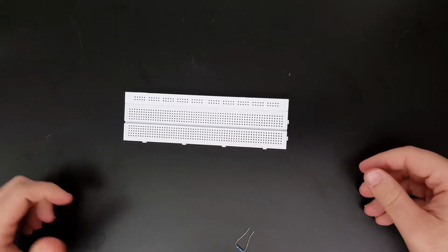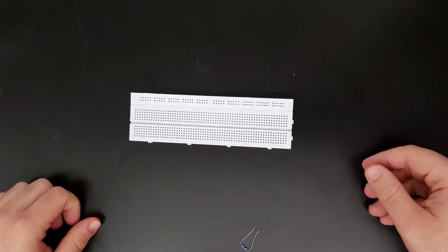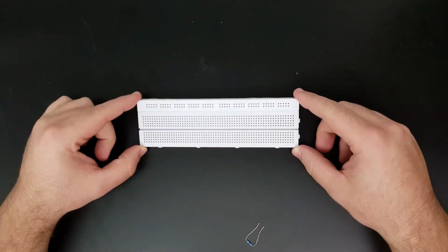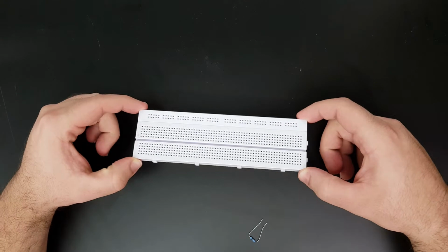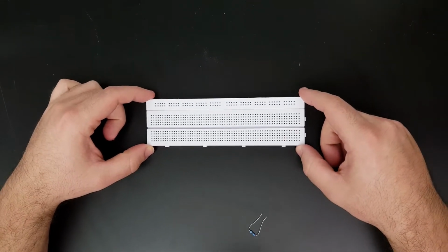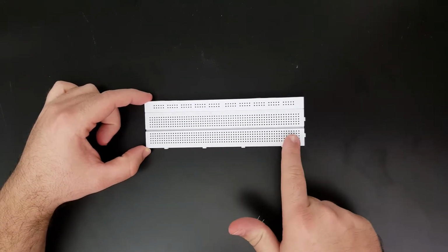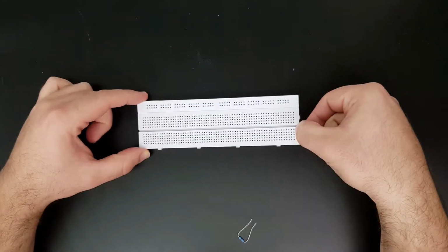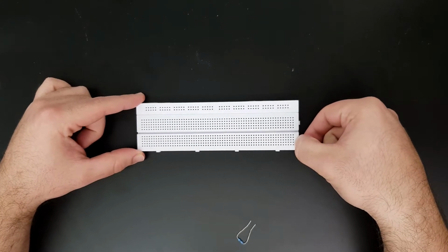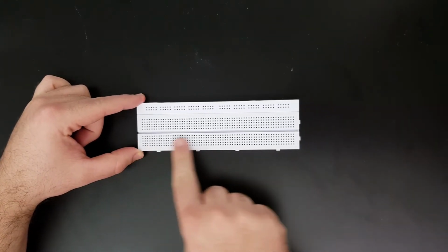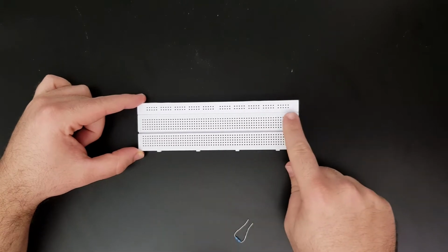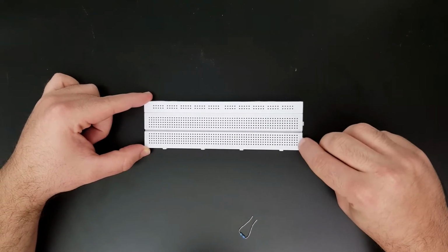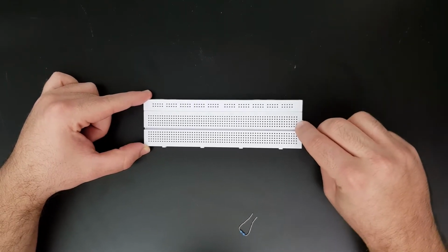I'm going to introduce you to the main hardware that you're going to use on the lab one. This is a breadboard for those who never used the breadboard before. It's a way for you to connect your components. In this area of the breadboard, all the connections are in this direction. So all these holes are actually the same point in the connection. This area of the breadboard and this area of the breadboard are isolated. So if you want to connect this area to this one, you need to use a jumper here.